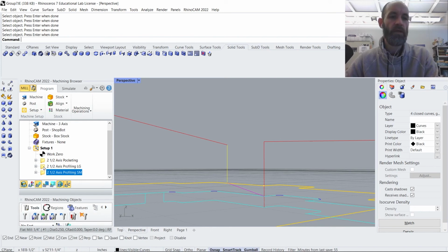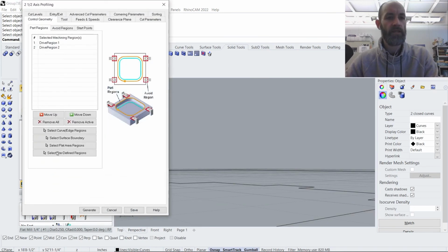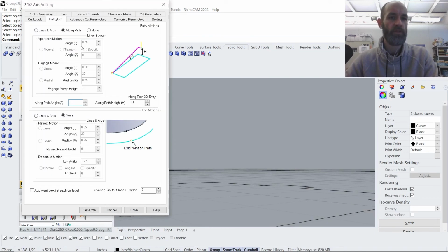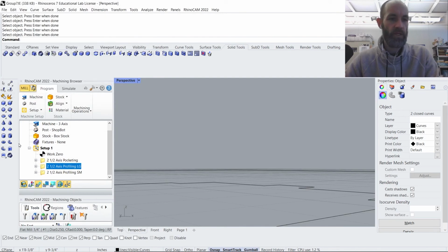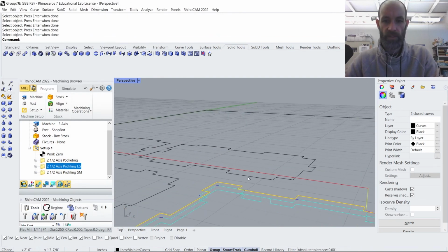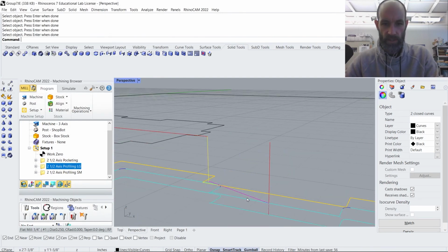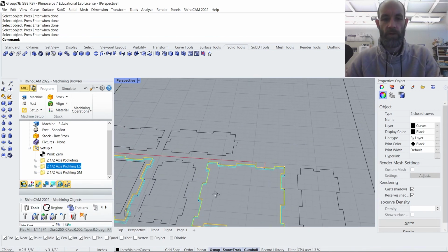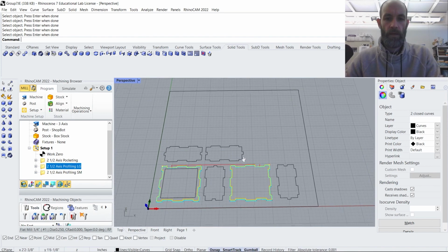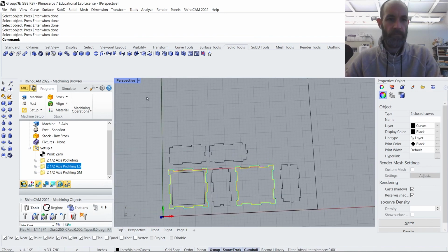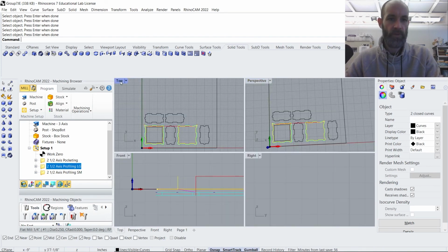So let's mimic that in the other one for the large objects. Entry and exit. Rather than that, we'll select 0.25 and generate. Zooming out, we'll see that here it comes just into contact with the face and then enters at an angle and then proceeds to follow the path counterclockwise. All right, I'm feeling pretty good about this one. We'll return to the top view.